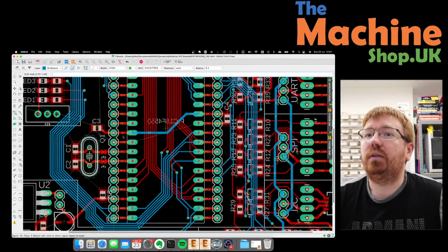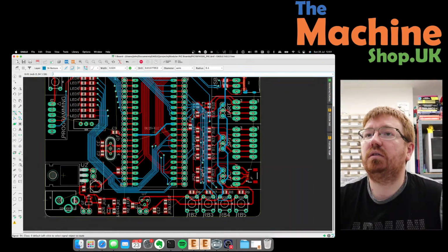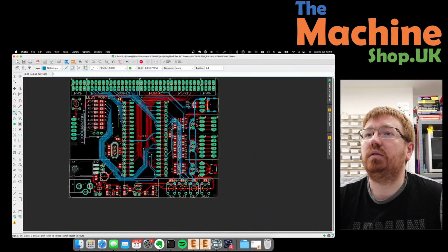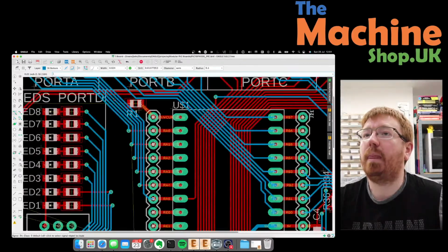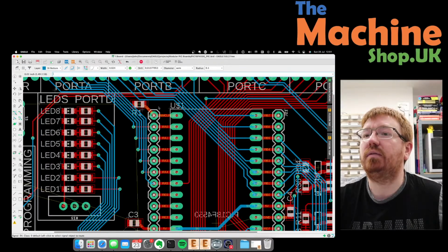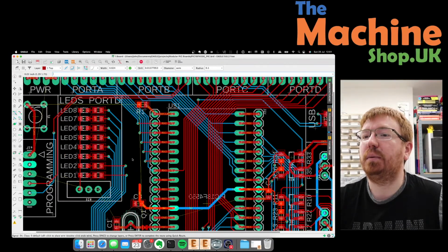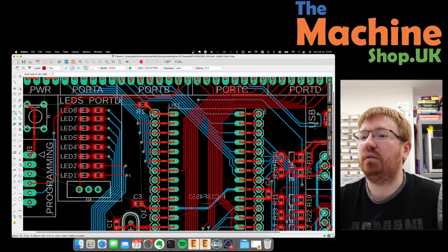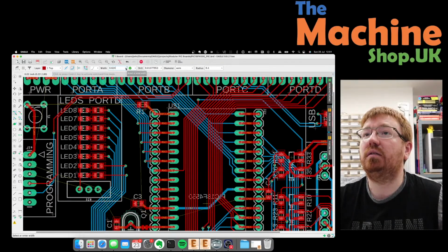Great. That's the 5 volt there, which... Where's that one wanting to go? Oh, that's that. There's a resistor there that needs 5 volt. Okay, that's nice and easy. That is only a pull-up, so that doesn't need to be a big fat cable. Cable? Track?